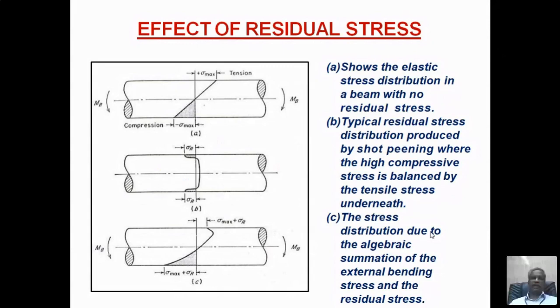And the SN curves we did for the... You see why I am showing this curve is. So this line, if you see, a lot of SN curves are here. The bottommost one is for the IIW fatigue class for this material. The material is ferritic stainless steel. We did for the 409M joints, unnotched specimen. For that material, the IIW recommendation is that it should have this line. So all the joints have performed better than that.